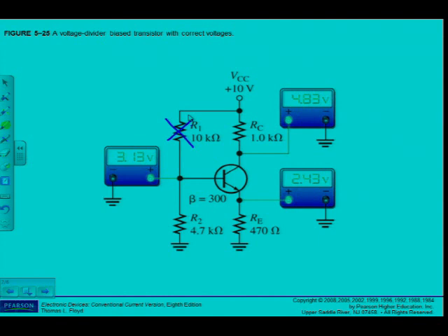What's going to happen in the circuit? That's why I said you must understand how the circuit works. Remember I said if I want to use the circuit for linear amplification, I need to bias it first. In this case, as we've seen, most stable voltage divider biasing will give me the most stable Q point to do my amplification from. But if R1 is open,